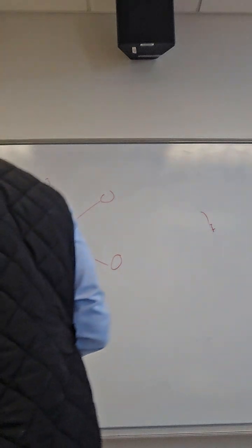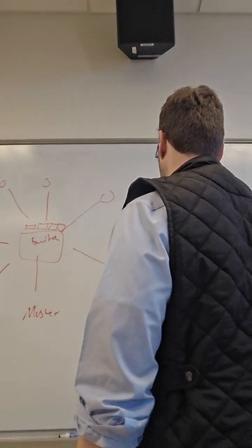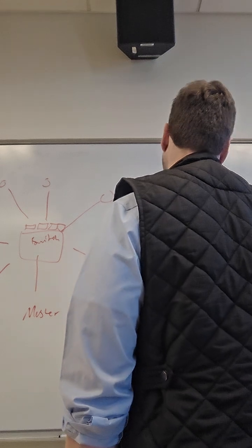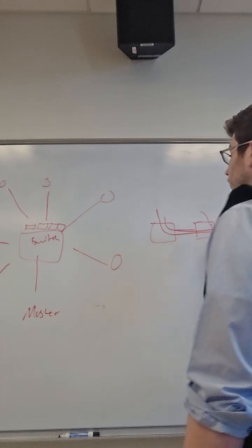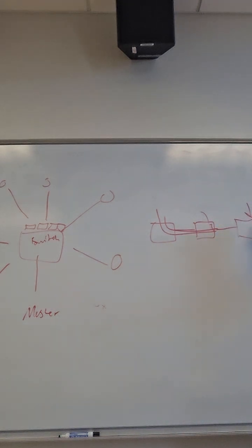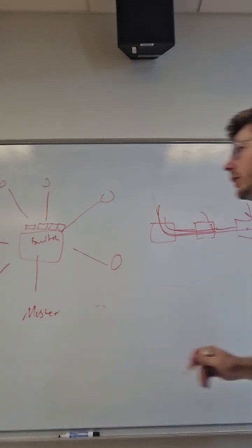Okay. Daisy chaining is when we go from one into the other into the other. So if we want to talk to this device, information would have to pass through these first two devices. This is the way that this is typically done: if we are addressing this device, we send data to all devices. They can all hear all the information, but they only care when we say their name. Essentially, they don't perk up and start paying attention until we address them. So they just ignore everything else unless they're addressed.